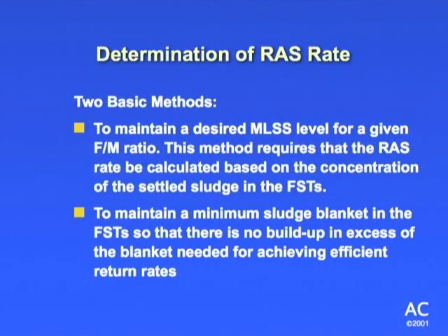Okay. I'm going to go through two different ways of determining return activated sludge rates. And again, this is all part of your bag of tricks, because we want to be consistent with our return rate, because that's establishing your food to microorganism ratio up in the A zone, your A selector, okay? So you want to be consistent with what you're returning up there to meet your influent flow. But there's going to be times where you can use this as a tool too to help maintain the proper function of your clarifier as well.